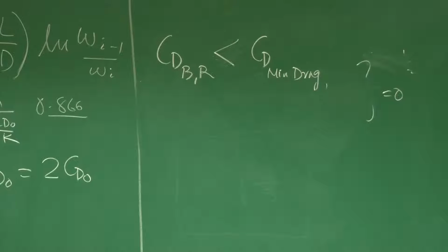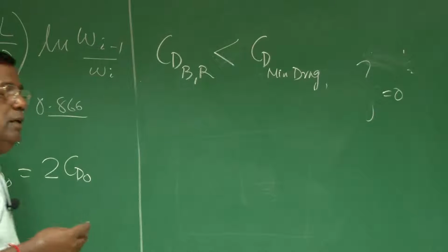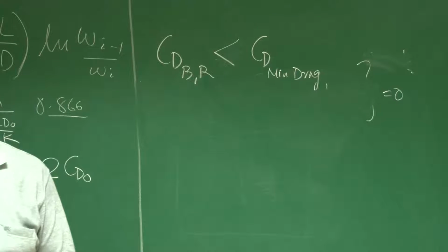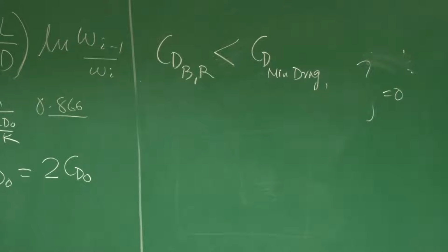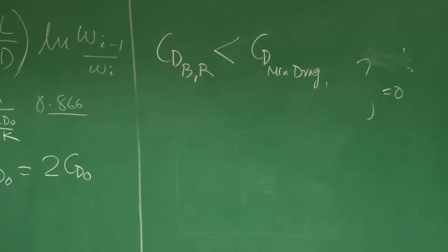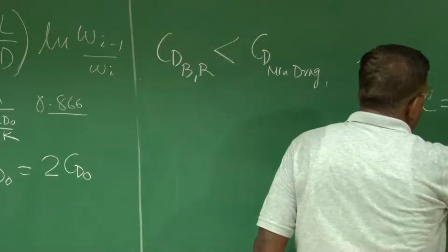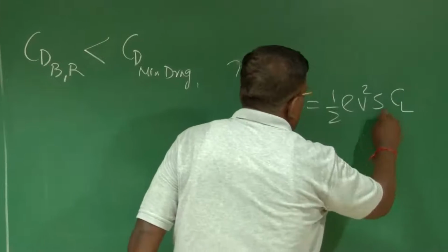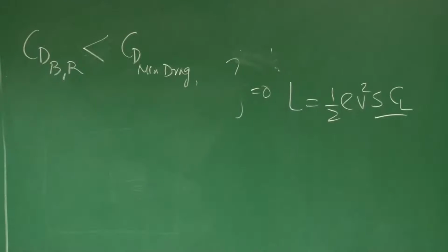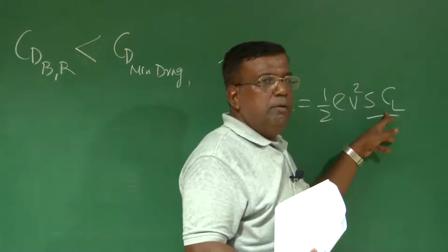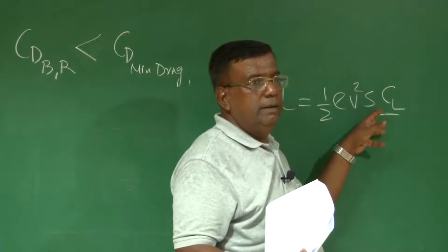Please understand, whenever you are designing an airplane, the dynamic pressure plays an important role. Make it a habit of taking along with your dynamic pressure, because even lift, when I write lift equal to half rho V square S CL, I have seen most of us psychologically get locked to what is the CL value? At the most, what is the wing area, right?